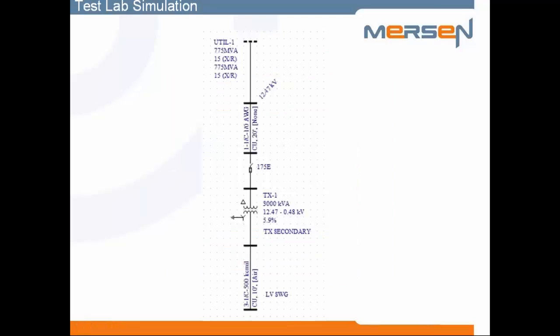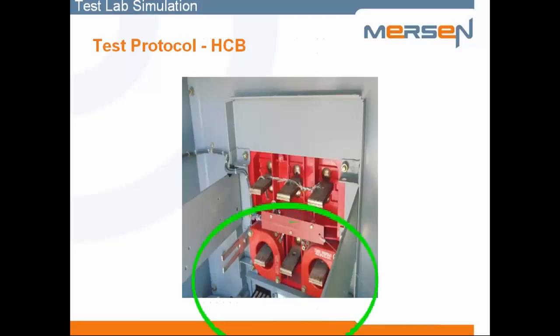Modeled in EasyPower, what you see here is that we figured there was about 55,000 amps available fault current. With the 175E as the sole protection, the incident energy was well over 400 calories at 18 inches. Note that the primary fault current at 1247 was 36 kA, well into the current limiting range of the 175E fuse.